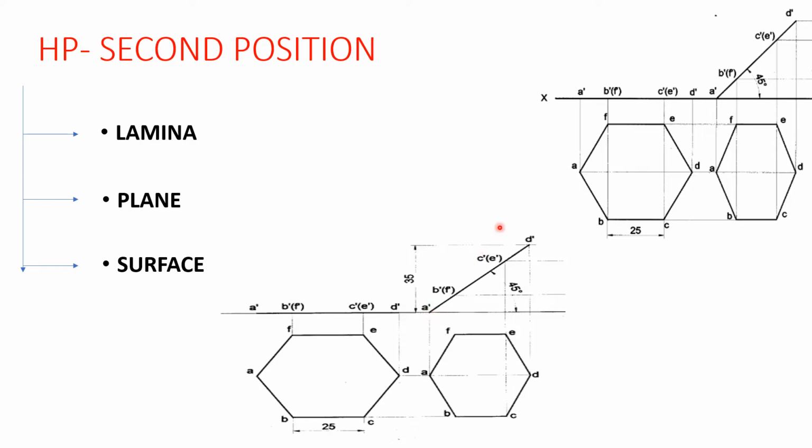From there you cut an arc equal to the front view of this line. Then it intersects at some point. You go to the trim option, trim both things, and move this line from the left hand and keep the left end at the center of the arc. Then you rotate and place this one at the dead end. Then easily you will get the inclination.